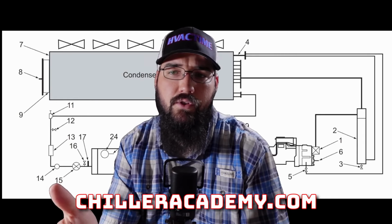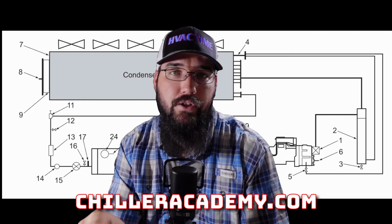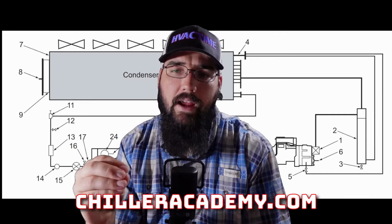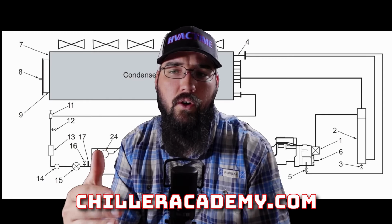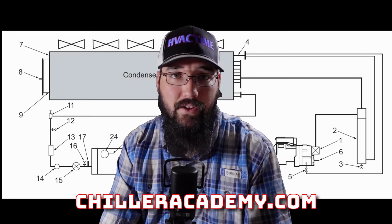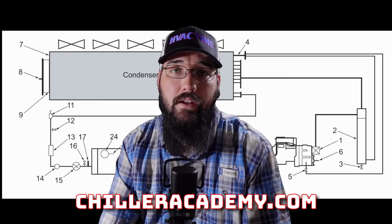Now, instead of showing you an RTHD in the schematic, I felt this one was far simpler, and the only difference would be you change out the condenser. RTHDs have much more complex oil management circuits, and there's a lot more going on there, but they're just one compressor. And so there are going to be some screw chillers that you come across that are just one compressor, maybe a very large compressor. An RTHD is an example of that. A YVWA is an example of that. They're one single compressor. They're just really big, and that's how it's able to control.